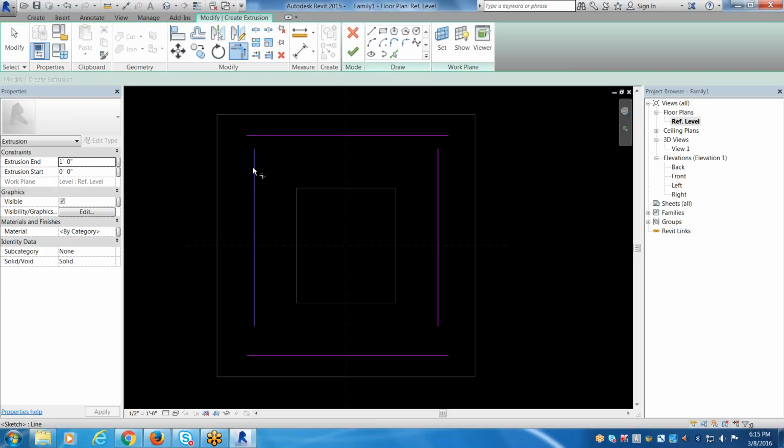TR is the trim. Just like fillet or chamfer, you pick these items and trim them together. TR, and then pick two items. The command is sticky, meaning you can just keep clicking. Good? Okay.